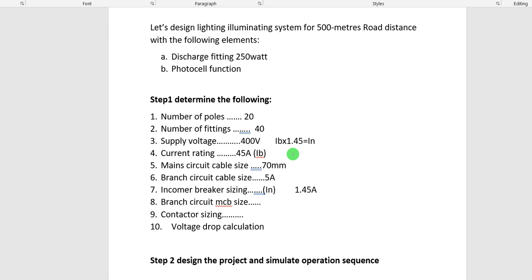Example, now, I have 5 loads put together, and those 5 loads come up one after the other whenever I energize this IN. Then in some instances, all of them will come up instantaneously. So for this breaker to be able to withstand that simultaneous engagement, you should augment the size to be able to carry your IB if they are coming up instantaneously.